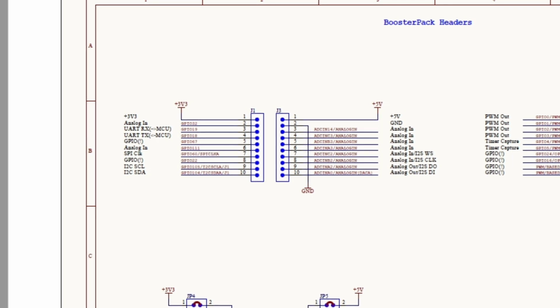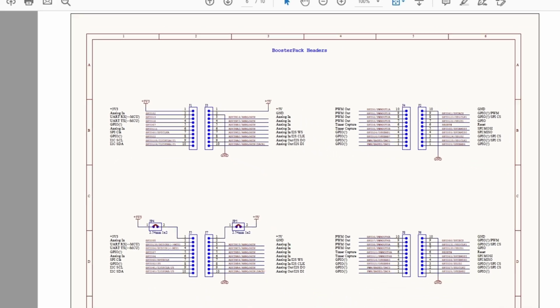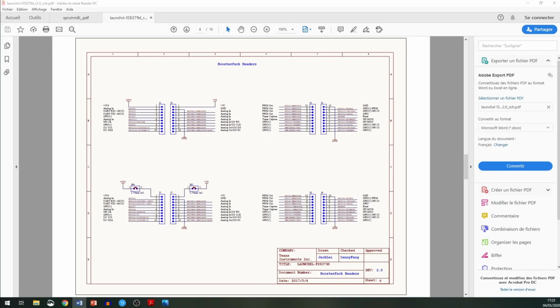You could connect these analog inputs to any different source voltage between 0 and 3.3 volts. The voltage reference of ADCA and ADCB is 3 volts. This means every voltage over the reference voltage will be considered as 3 volts or 4095 points as conversion result.